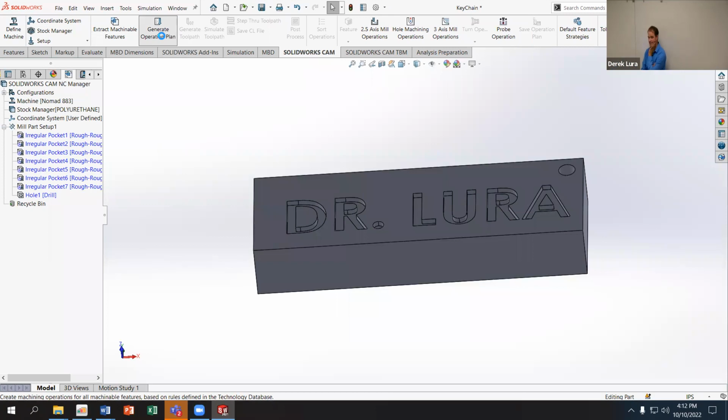There is some optimization that can be done here to make the machine take less time, by not doing tool changes as frequently or doing certain operations in specific orders. We're not going to get into all that. You could spend years as a machinist learning what the best practices are there. We're going to be more concerned with just being aware that we have to do a lot of these operations sequentially. There are some sequences that are preferential to others, and you can control that in the software if you want to. Hopefully this won't take too much longer to generate my plans. If you had fewer features, it may generate a little faster for you than it's doing on my end. But we'll wait a few seconds and see if it goes through. My attempt at being patient right here.